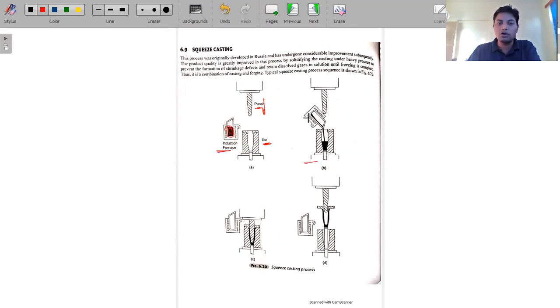This is step two, where we fill the molten material into the die. Also, as I said, if an excessive amount of molten material is there, it will be brought out. I will not produce the glass as only one piece; I will produce thousands or lakhs of pieces. So in one process I get to know how much material is needed, and accordingly I fill it. The same process is applied here. It is filled up to this level only, not up to this. We have to keep this in mind, as it will save our time as well as cost and money.